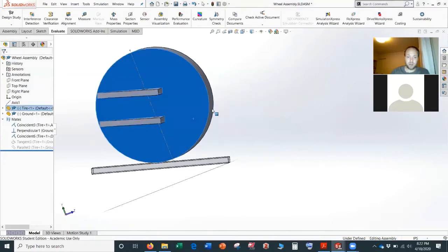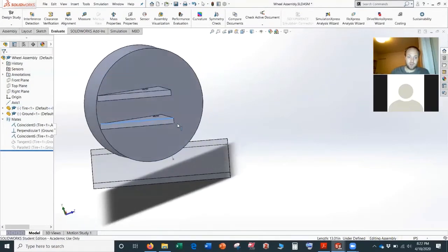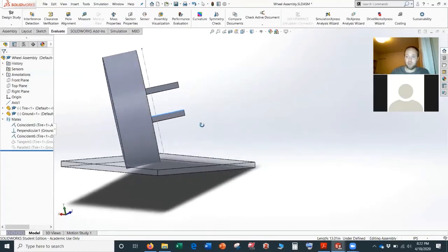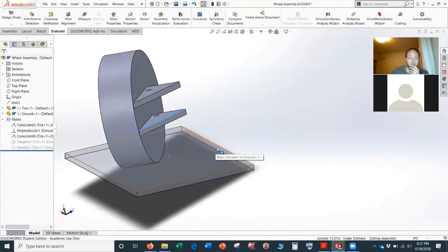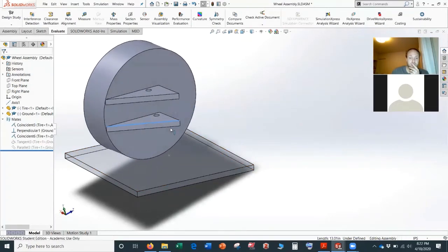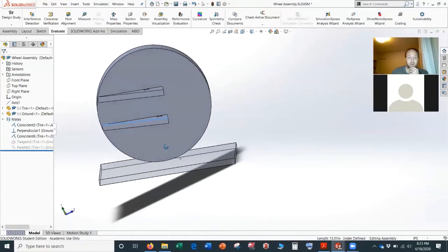But you'll see some of the downsides, right? So as you start to come way back here, you start to have large camber of your tire. You're going to start to roll on just one edge. You just start to ride on the outside edge of your tire, which, to a point, is not great, right? And I think naturally having some caster is critical, just to make sure you have some trail, because you go crazy unstable when you don't have any trail. Especially imagine when you have some pitch forward as you're stopping, you want to make sure you continue to have some positive trail even in those cases.